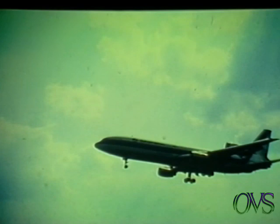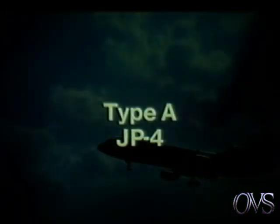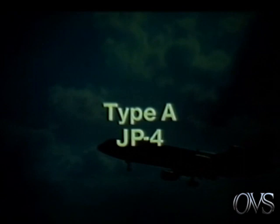The next group of products we will look at are Amoco jet fuels. We pump two kinds of jet fuel, Type A, which is a petroleum distillate, related to diesel fuel and kerosene, and JP4, which is a petroleum naphtha mixture like gasoline. JP4 is considered a flammable liquid by the Department of Transportation. Type A is a combustible liquid.